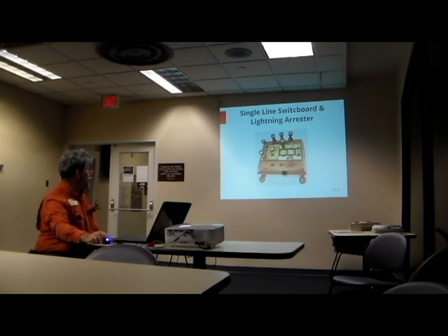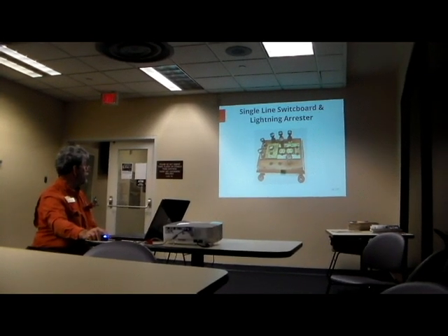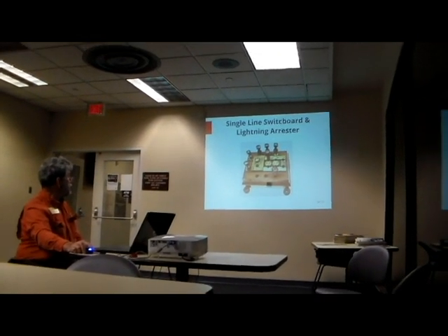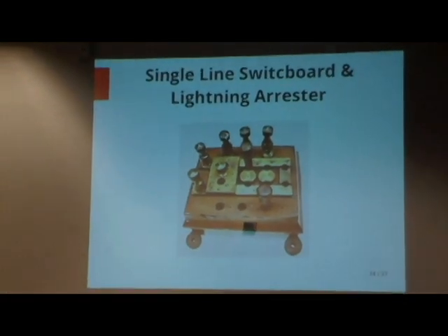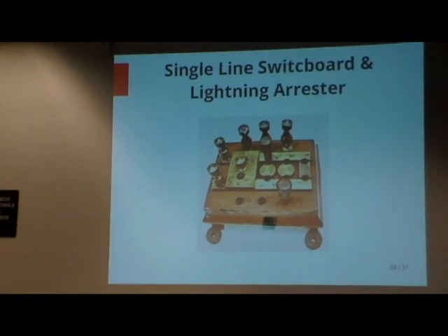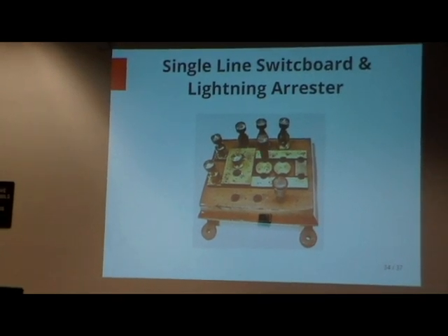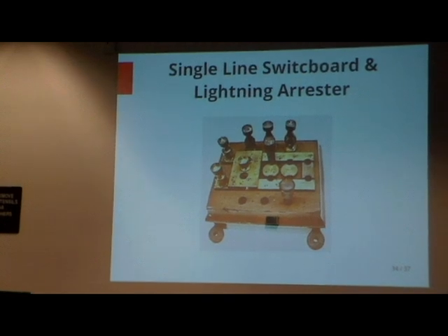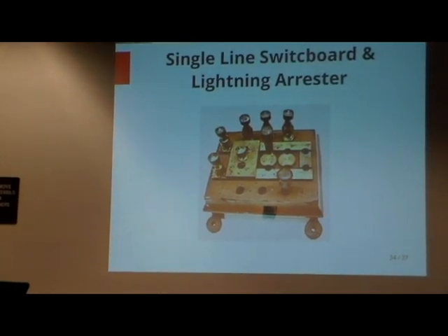Now this is a later version still of an arrestor. I actually own one of these. And this is the electrode plate. The electrode is this terminal. The grounding electrode conductor would be attached to this terminal right here. And this plate is a little thinner than it would need to be to actually contact the two line straps.